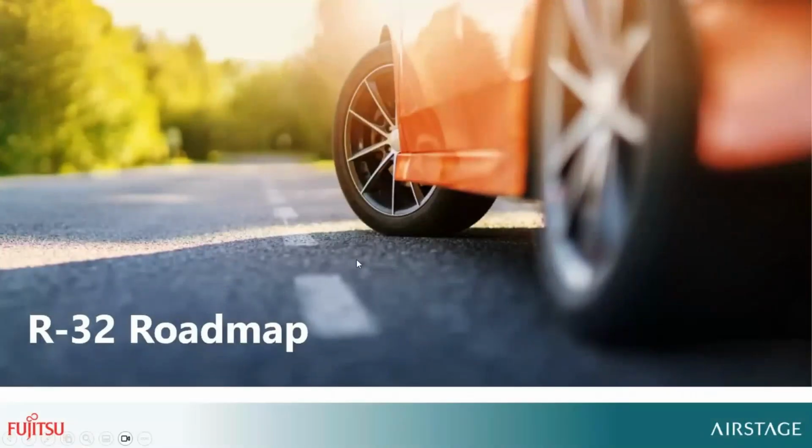Well, there's one more question about fireproof shafts, and I just want to address that. ASHRAE 15.2 is very clear that you do need a fire-rated shaft, either naturally ventilated or mechanically ventilated. But I just want to highlight that ASHRAE 15, as of May 30th of 2025, earlier this year, they eliminated that from ASHRAE 15. So on a multifamily building, there's actually a way that you can apply both standards to that multifamily building. ASHRAE 15.2 applies to the apartments, while ASHRAE 15 applies to the shared common areas.